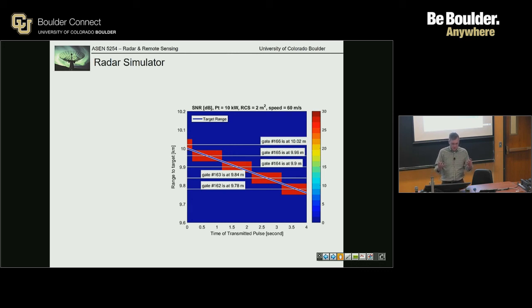If your system has a large noise variance, all you care about is that your signal is larger than this noise variance. If you have narrower variance, it's the ratio between the signal and your noise floor that's important. So it's the ratio that will extend from one system to the other.